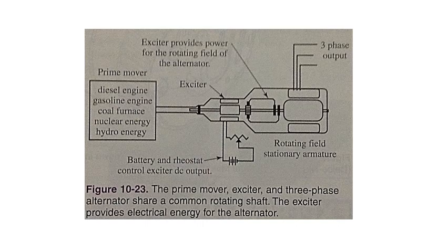The alternator. The AC generator, also called an alternator, is used in the charging system of all US automobiles. Figure 10-24 shows the inside of the unit, including a built-in voltage regulator to control output. The output is rectified from alternating current to direct current for charging the battery and other electrical devices in the car. Manufacturers say the alternator has some advantages over the DC generator. These advantages include higher output at lower speeds, as well as trouble-free service.